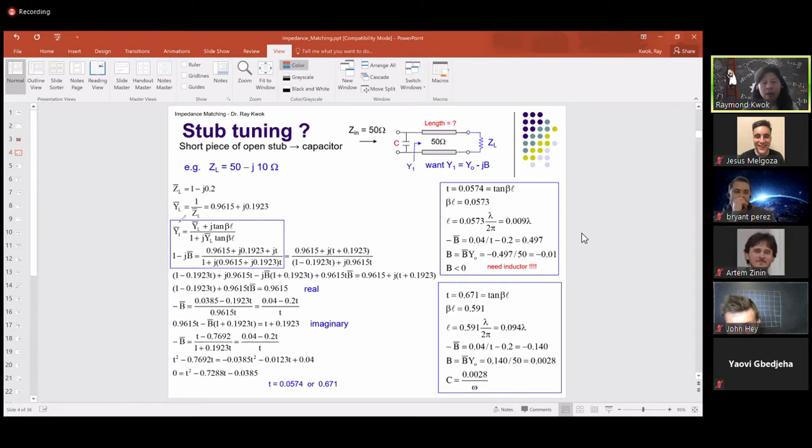I know the load admittance after the transmission line, I call it Y1. I want to match the real part already, leaving the imaginary part as a variable, which I don't know yet. So that means the normalized Y1 is equal to the normalized Y0, that's 1 minus j B with a bar. Again, the bar on top means normalized. So this is a normalized susceptance.